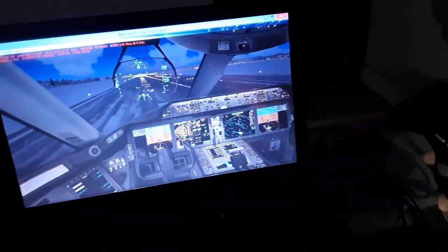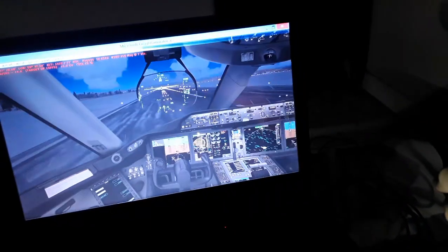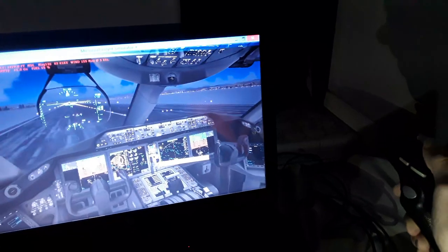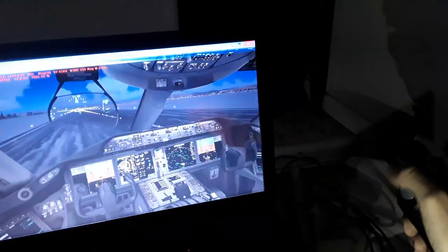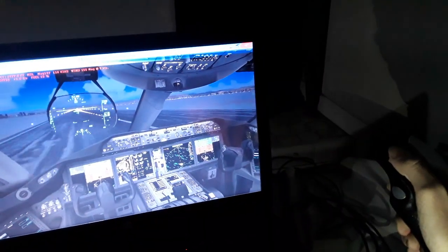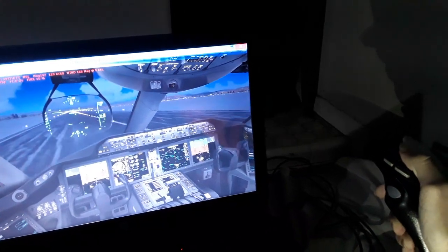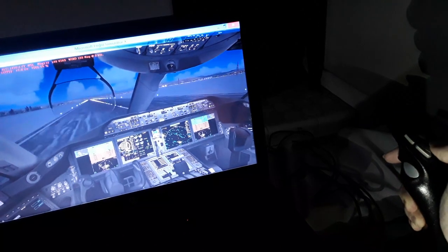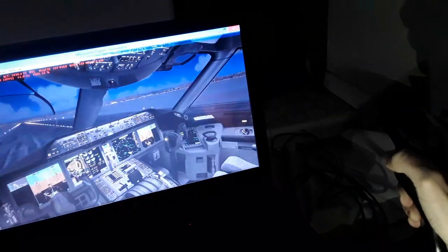Advance the thrust levers all the way up. We take off ground thrust. So we are in the takeoff roll. Press the rudder. Press actually the yoke a little bit down. 100 knots, 110. V1. We rotate slightly, 9 degrees. So we have the rotation.